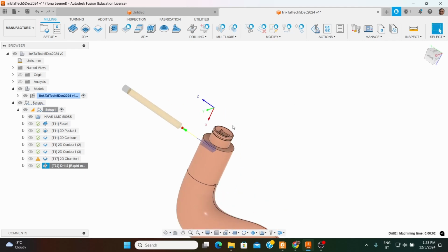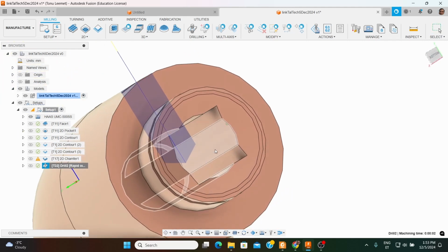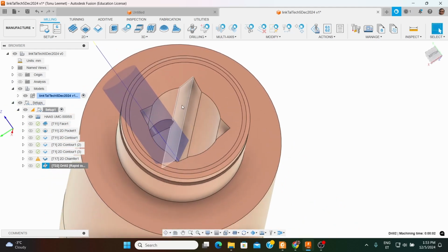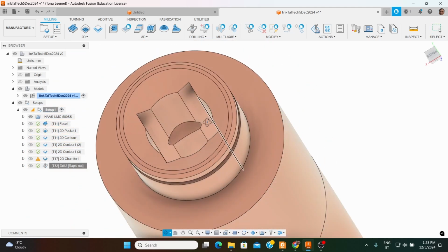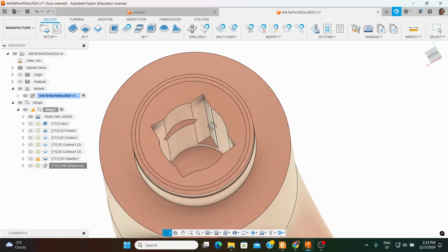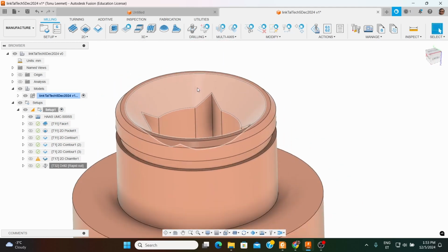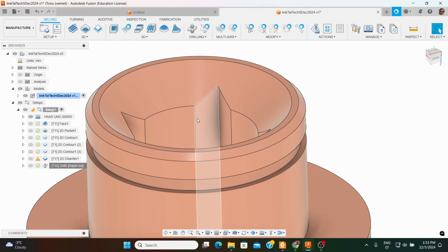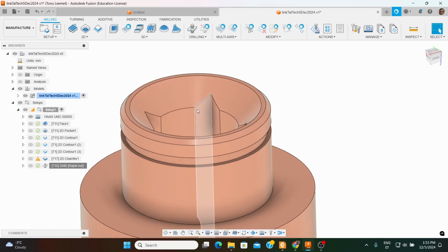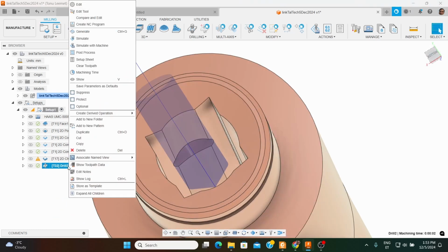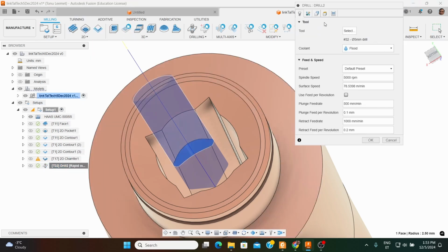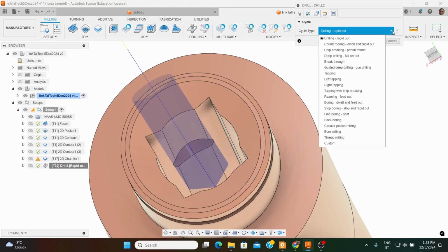Anyway, there might be the question also with doing this hole. For this hole, you would need to have some kind of special tool and another machining operation. I'm not totally sure by heart. Is it broaching in English? Could be. You could try to do it with a simple drilling operation, honestly. If you have the tool, you can try to do it with that, because if I edit my drilling operation and go to this cycle, I see I have these different cycles available.